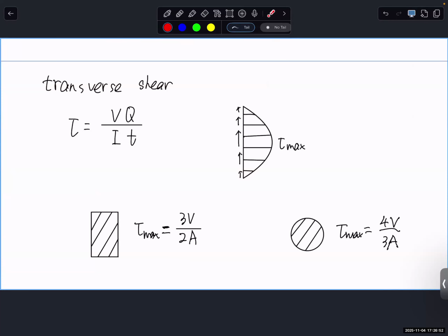So tension compression, and torsion, and bending moment bending this way. Transverse shear basically means this is shear. Let's say I clamp on this side, I fix this side as a reaction and apply a force here. Then this is transverse shear. And for calculating the transverse shear stress generated by transverse shear force, this is the equation, and it is the shear force, first moment area, this thickness dimension of the cross section, moment of inertia.